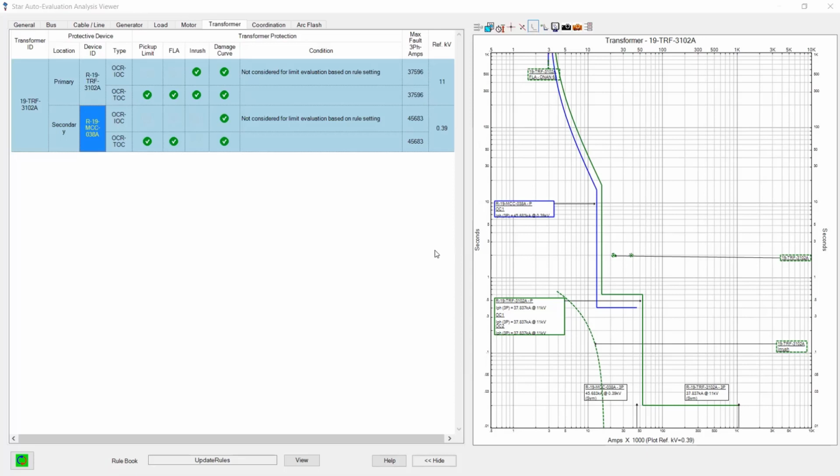So the rated current of the motor, for example, is changed minorly. You can have similar types of issues. So with star-out evaluation, you can easily compare if your predefined criteria, that could be, for example, a percentage range from the full load amps in which you want to have the setting, is matching or not.